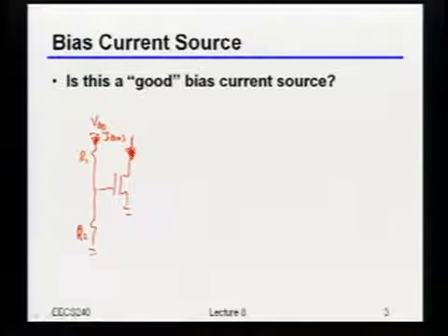Now, by the way, you said relying on one transistor gives you horrible matching. It's only one transistor, so matching doesn't exactly mean something. But what are you really saying when you mean matching? It doesn't track the VT with... Oh, okay. So now everybody said a bunch of things, right? The big problem here is variation, right? In other words, if I just set some voltage there, who knows what current that's going to get me?